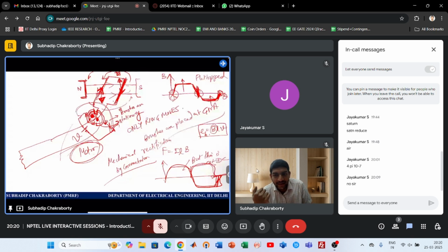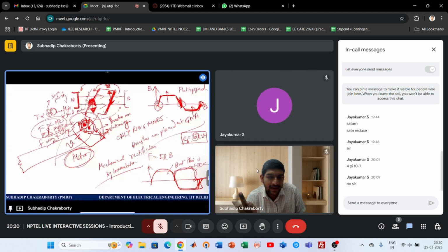Same polarity of voltage means the terminal voltage, at which we are tapping out the voltages. For a motor, if I give plus 250 volts, and for the generator I take out from the same ports, labelled plus and minus, and I try to take 250 volts from the generator, please understand that I have to rotate the generator in a different direction than I did for the motor.